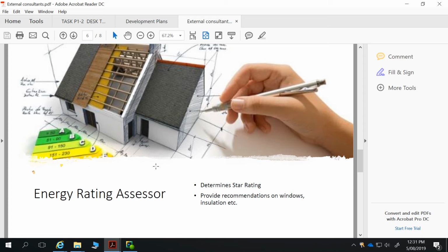But if you've got a decent appreciation for passive solar design, thinking about sun in winter, no sun in summer, and you build with a concrete slab, it's going to be pretty easy to meet that star rating. There are various other permutations around energy rating as well. Sometimes you see some absolutely shocking examples of buildings. You think that would be horrible to live in in terms of the heating and cooling load. It's not only the use of reference buildings, but with apartments and things like that, you get a general star rating for a development rather than for individual units.